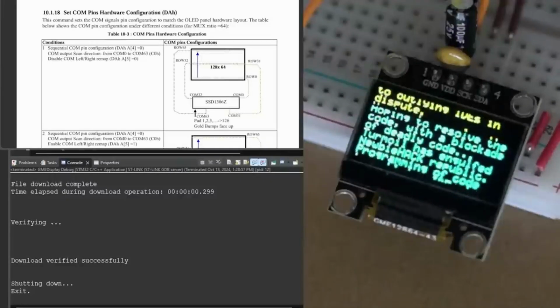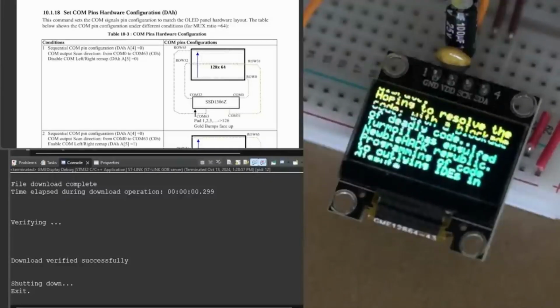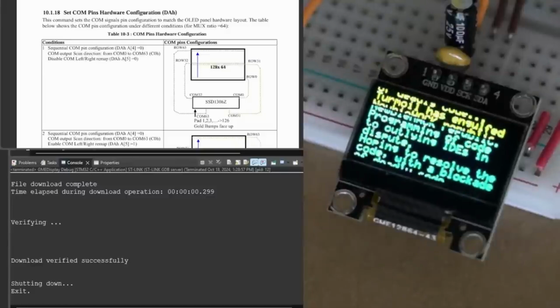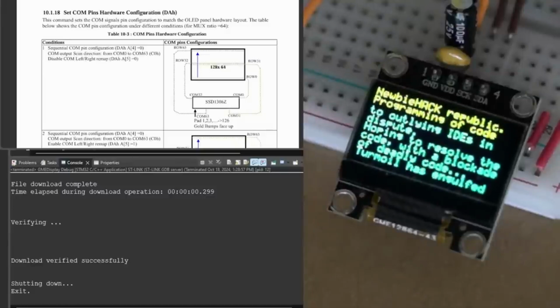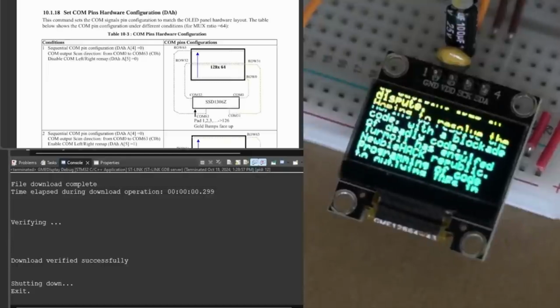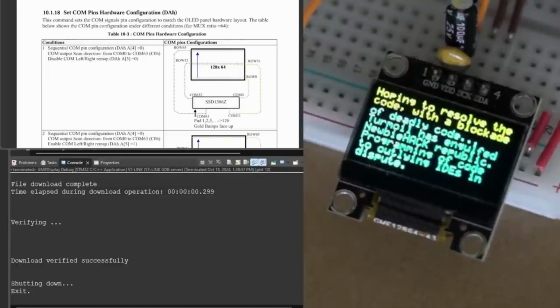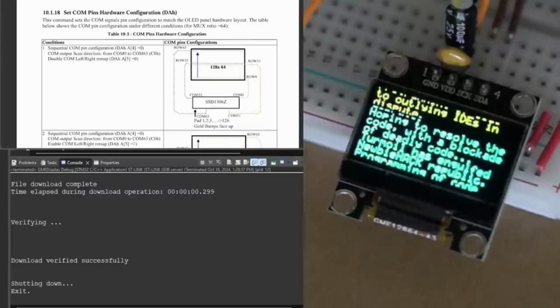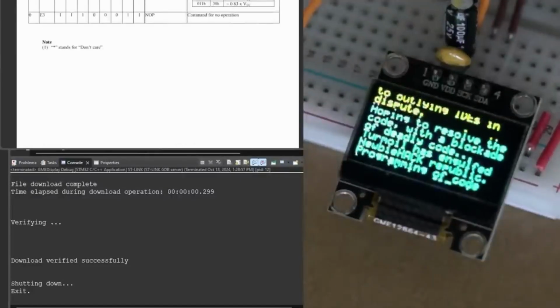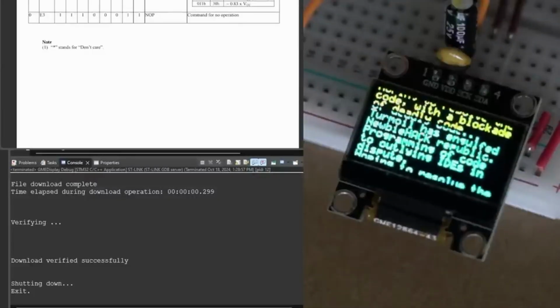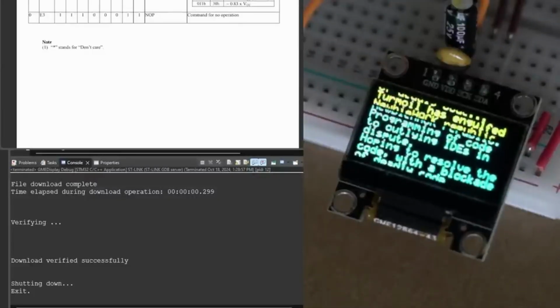Program the oscillator frequency FOSC, that is the source of the clock, if the clock pin is pulled high. The 4-bit value results in 16 different frequency settings available as shown below. The default setting is 1000. It's not clear whether it's left justified. So if I made this one, yeah, that's 8. So how is this 80 in the default?